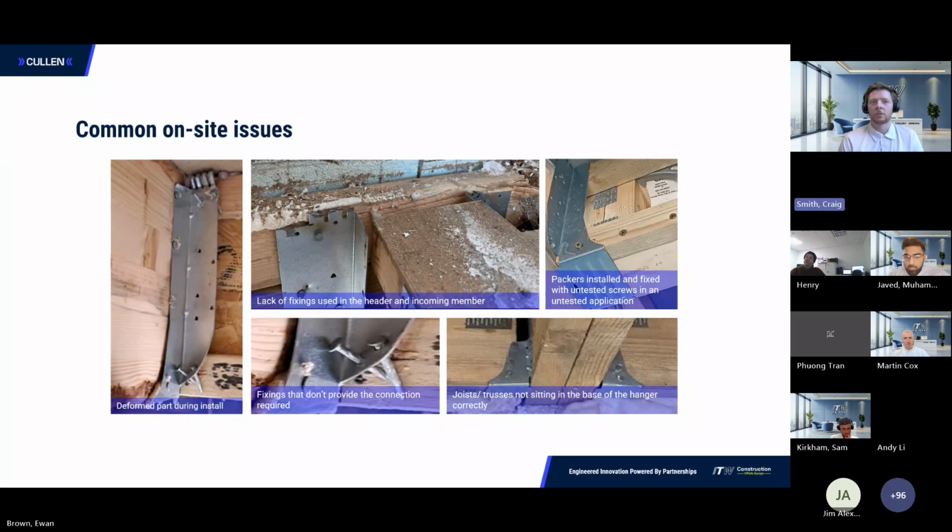Site issues can differ from the design errors, but are equally critical. Here we've got damaged or bent metalwork. I talked about those top tabs being crucial, and we can see there that they're not properly installed. The top tabs have been used maybe incorrectly. It's a weak fixing, so we can see some there that they're not actually in the timber. So that will definitely impact the load.